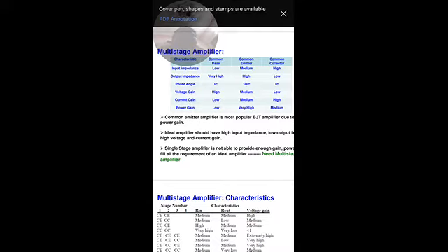So from the characteristics it is clear that we have both voltage gain and current gain possible with a common emitter, and it is not possible with the CB and CC. So we have a power gain that is possible with the CE, and it is not possible with the CB and the CC. So the CE is the most widely used configuration of the three types.